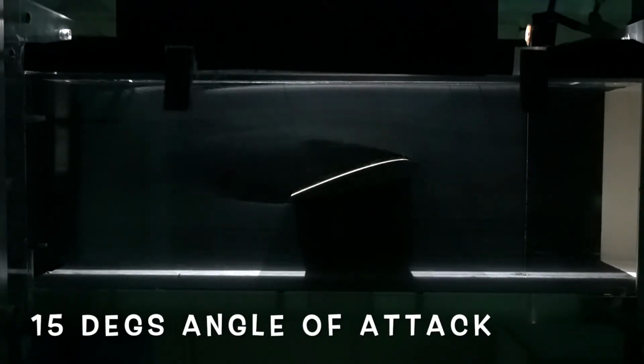So we bumped the angle of attack of the airfoil up to 15 degrees now, and now you can see we're in the full stall regime. Now you can see the separation point has fully moved up to the leading edge. You can see that there's clear separation at the leading edge now. And so now we're in the full stall regime where increasing the angle of attack does not lead to an increase in lift anymore, just an increase in drag.